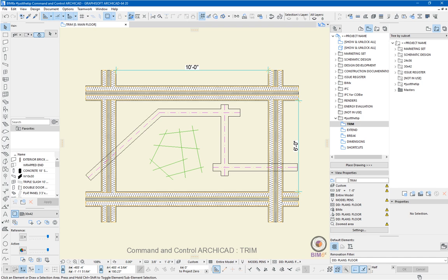There's a few simple things we're going to look at. The first one is just trim. Now there is a trim button somewhere on the interface. We can see it up at the top of the screen here. You pick trim, you trim your element, and that's it, finished. If you want to trim another element, you trim again, trim the next piece. It's quite slow because you're going backwards and forwards and you can only do one at a time.